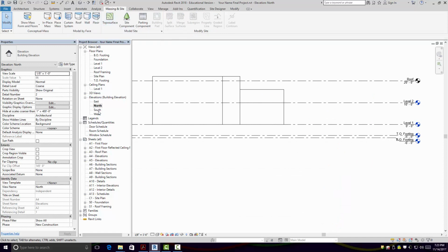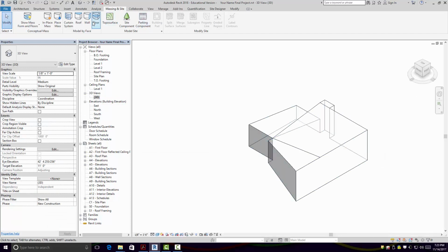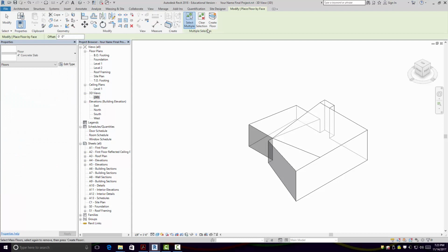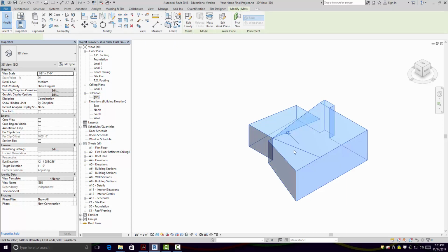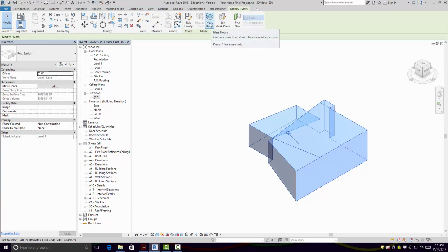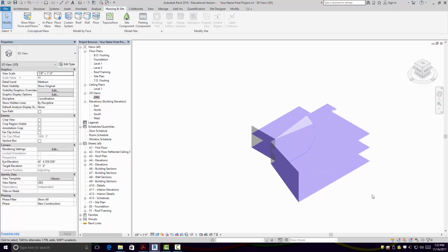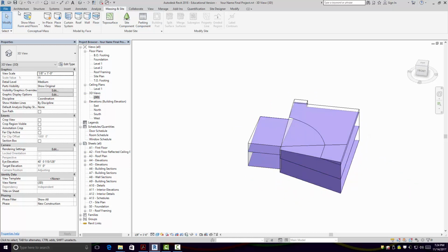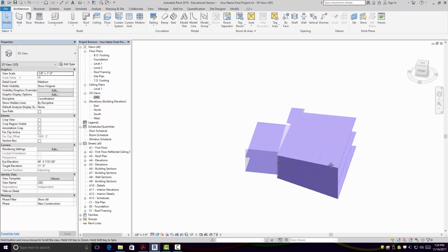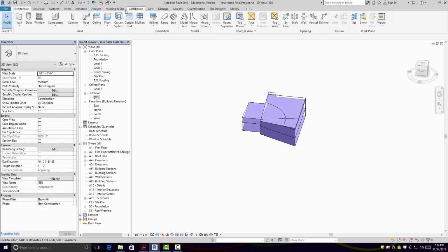So now if I go back to the 3D view, look at the 3D view, and I ask for the massing of the floors. I say floor. Actually, I don't want to create the floor yet. If I pick the model, I can add the massing of the floor. This is part of the massing, these floors. I think most of you have done this, right? I can actually add the floor to the massing by just simply picking the massing.